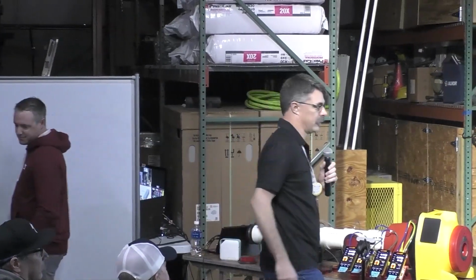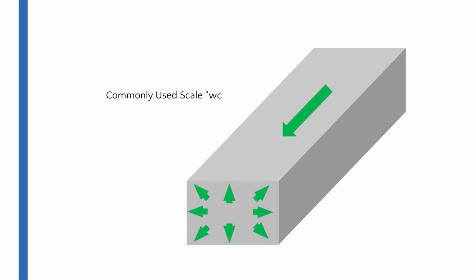So one of the first things we want to understand is static pressure, right? And what is static pressure? Static pressure is the pressure pushing out on that duct, and it's created when we push airflow into the duct, and it pushes a little pressure out.